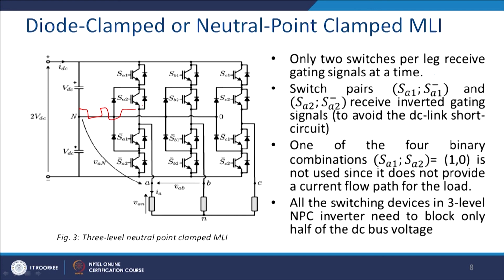Instead of that, we can connect a diode, and you can use the switch S2, and thus what will happen, these 2 switches, and similarly in the lower half this diode will conduct. So, instead of these switches, we can replace it by a diode. So, this is the optimal circuit you will get, and ultimately this is the diode clamp realization, where when you give pulses, accordingly switching will take place. So, what is the switching configuration?